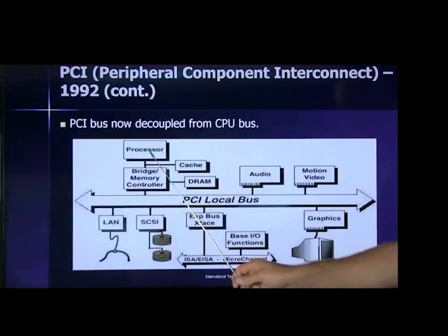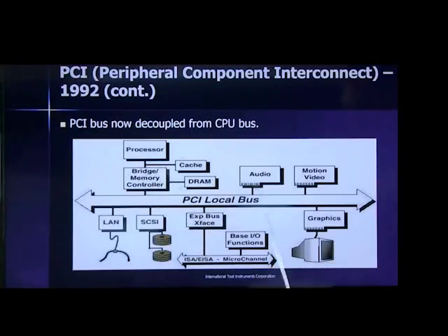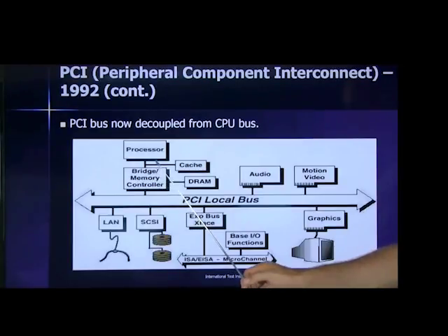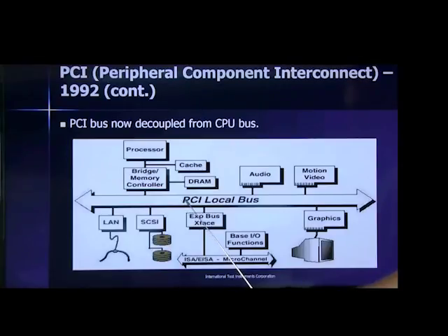If the processor then, by using a device driver for the device that is being accessed, accesses a register that the bridge recognizes as being mapped to a graphics card or another card here, then the bridge would claim that primary bus transaction, the memory bus transaction, and create a secondary transaction on the PCI local bus.